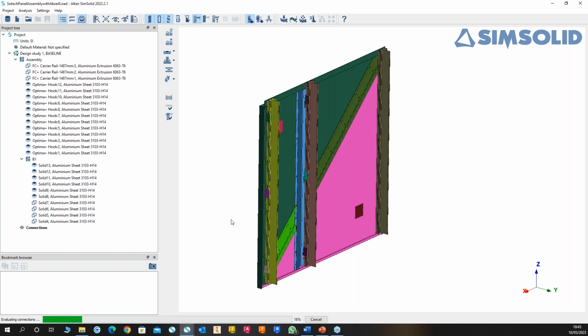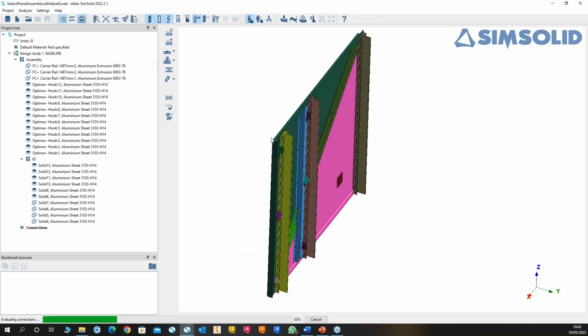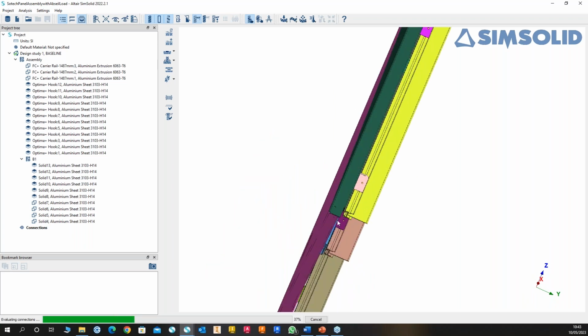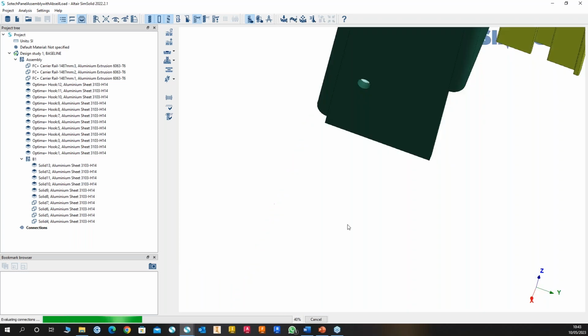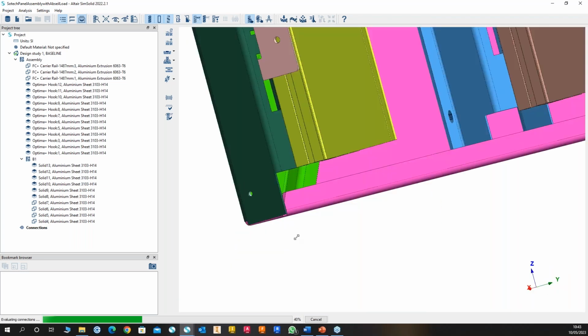You have to have a hex head so that it recognizes that. I use something called a pin, which I'm going to show you. I don't tend to model bolts, nuts, and screws in my models. So I put the holes in, and later I'm going to use a rotating pin to fix them, which I'll show you how to do.